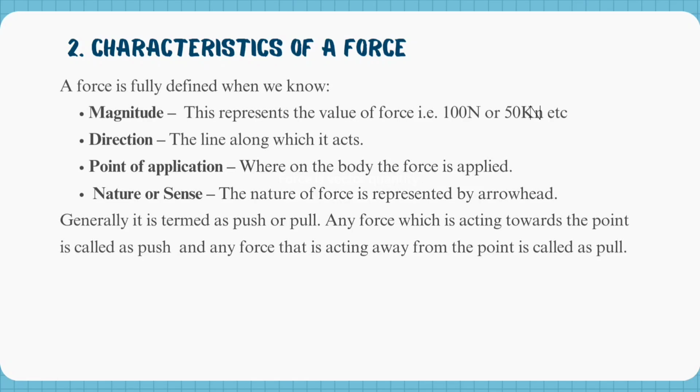And the direction means the line along which that force is acting. Point of application is where on the body the force is applied. And nature or sense means whether it is a pulling force or a pushing force, or we can say the nature of the force is represented by the arrowhead. Generally, it is termed as a push or a pull.